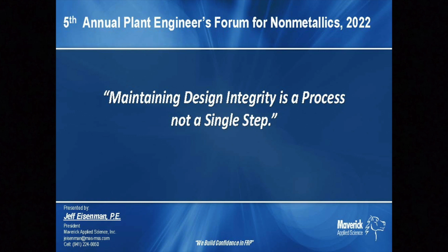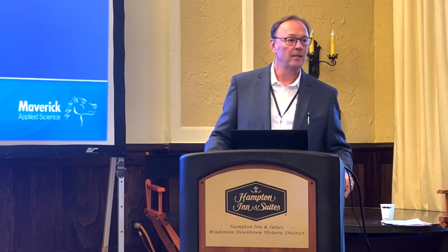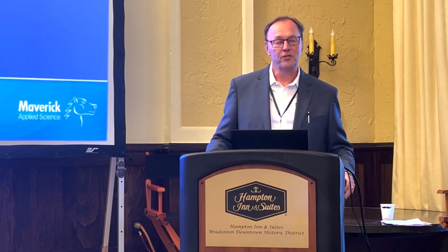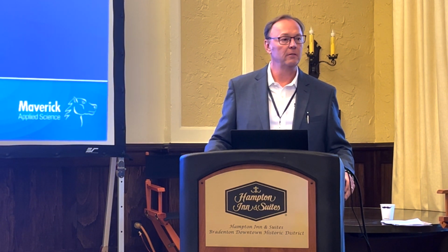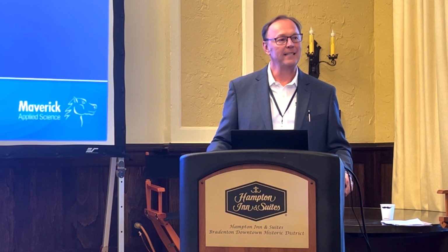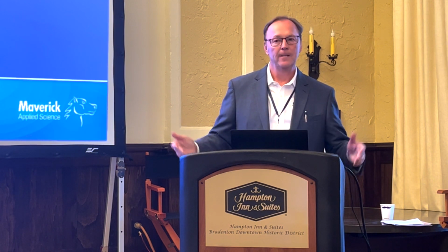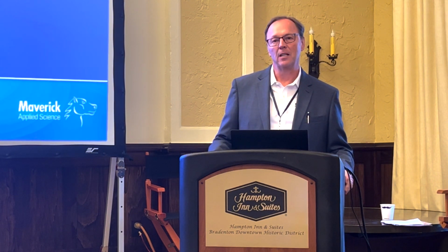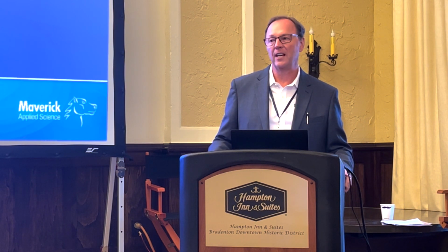So again, it's a process. It's not just a single step. There's definitely a recipe. It's something that you do on every project. It's not material specific. You need to have checks and balances in engineering and manufacturing and installation. It's not anything different than what the owners do in the plants for steel or concrete or any other material. If you're doing concrete, they take lump samples and do 28-day breaks and things like that. We need to have all the same steps in FRP, and when we do that, we generally have pretty good results.